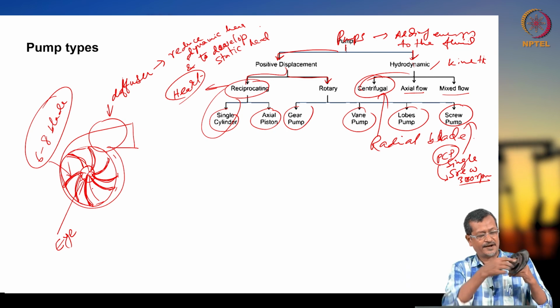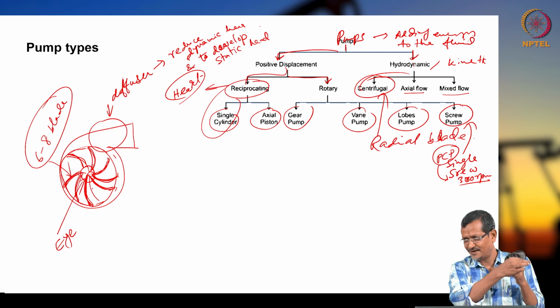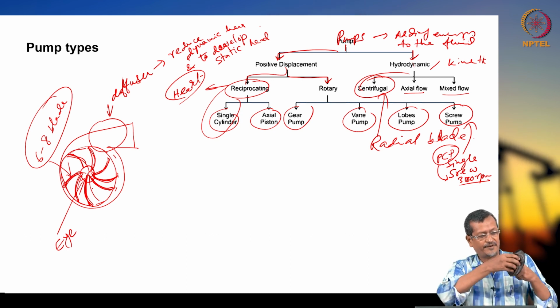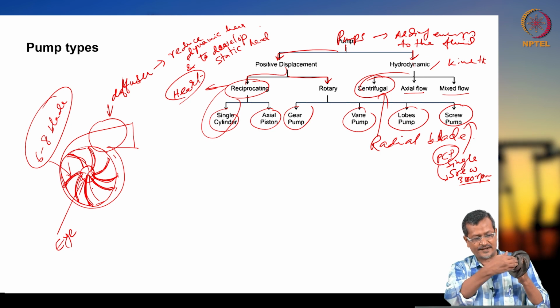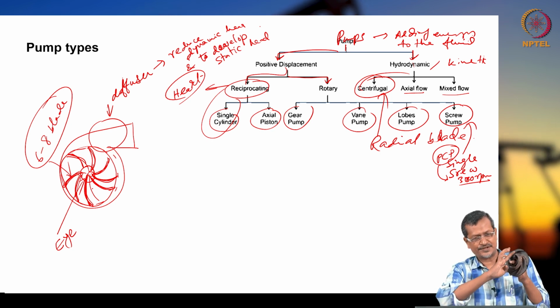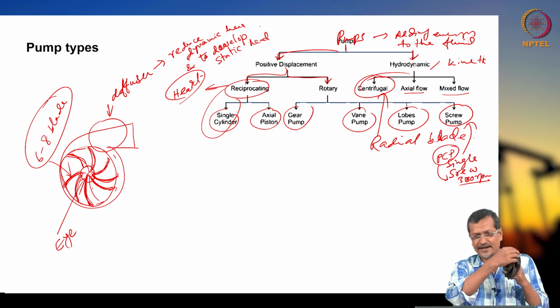Okay, and it is having some guide channel. You see the blades are there, solid metal. This will be acting as a guide channel. If you rotate at very high speed, fluid will be sucked in here at the impeller eye. This is the impeller eye. It will go through the channel and exit. When it is exiting, it will have very high velocity.